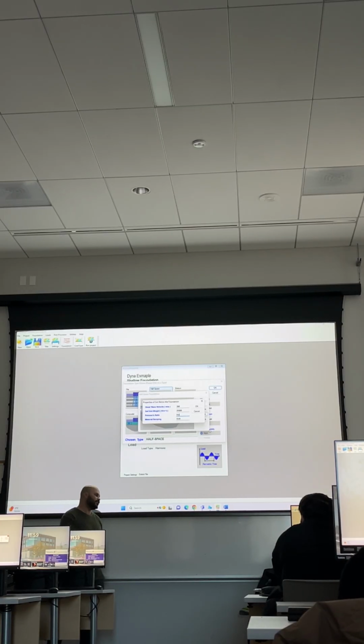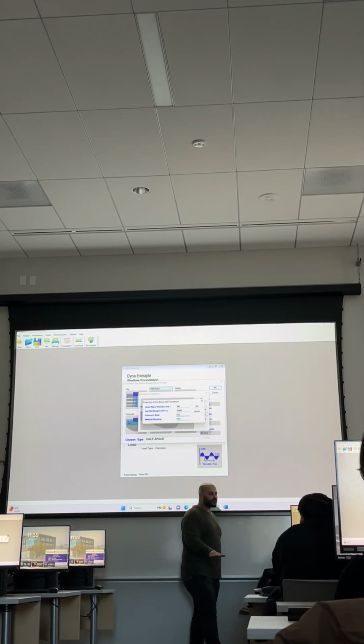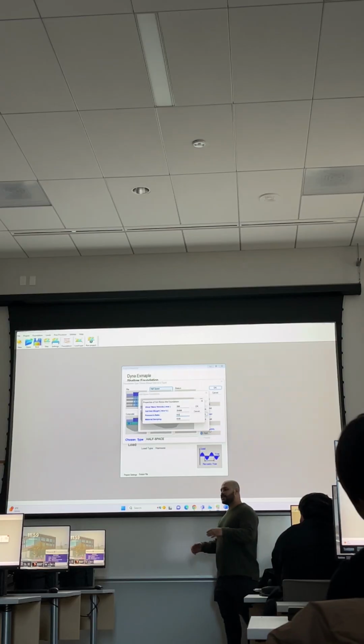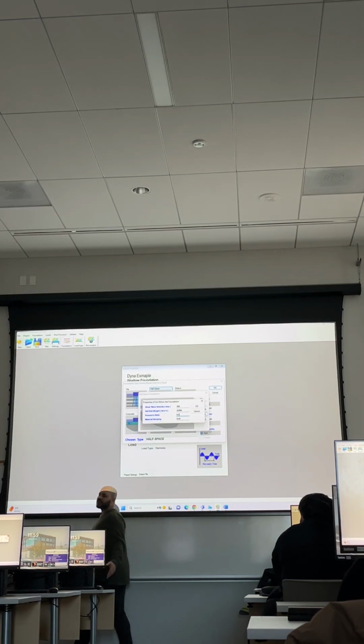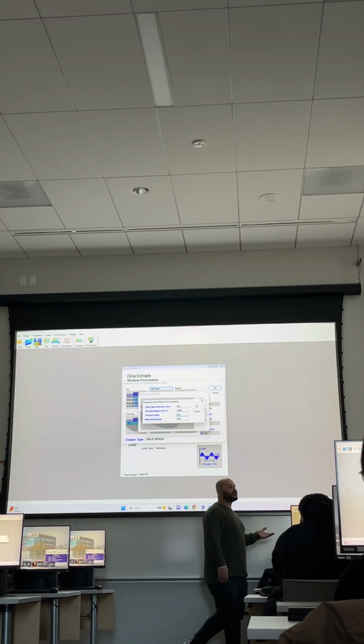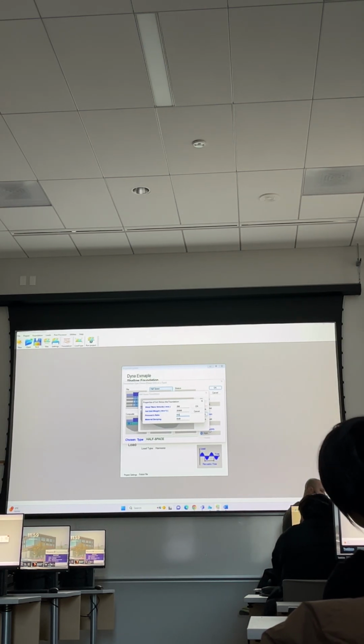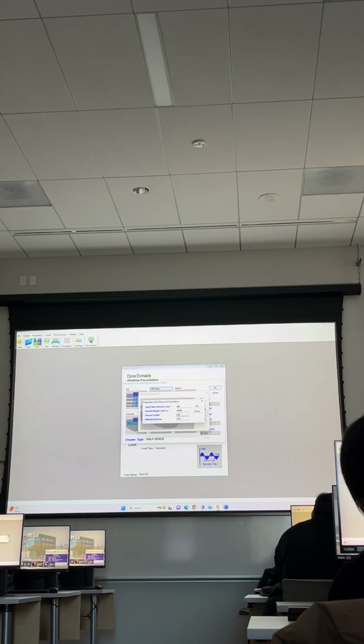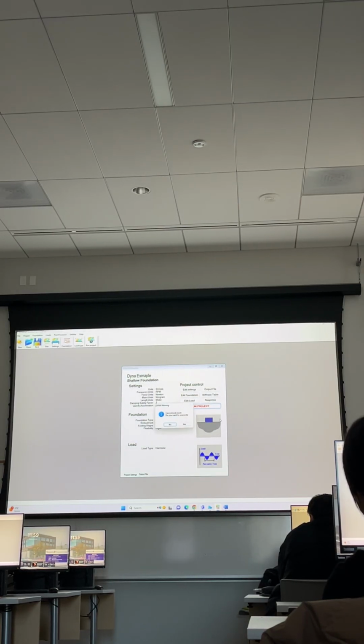So when you push the soil in the vertical direction, it will show the same strain in the horizontal direction. You can't compress the soil. This is a theoretical value, so you don't expect to get this in real life, but let me show you how it can affect the vertical stiffness. If I press OK here and run the project again.